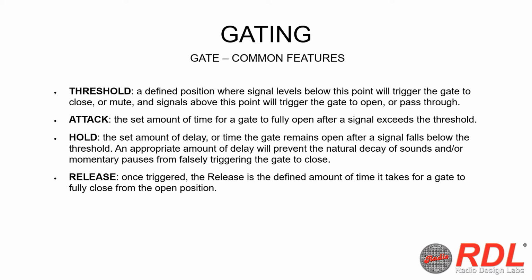Attack. This is the set amount of time for a gate to fully open after a signal exceeds the threshold. Hold. This is the set amount of delay or the time the gate remains open after a signal falls below the threshold. An appropriate amount of delay will prevent the natural decay of sounds and/or momentary pauses from falsely triggering the gate to close. Release.